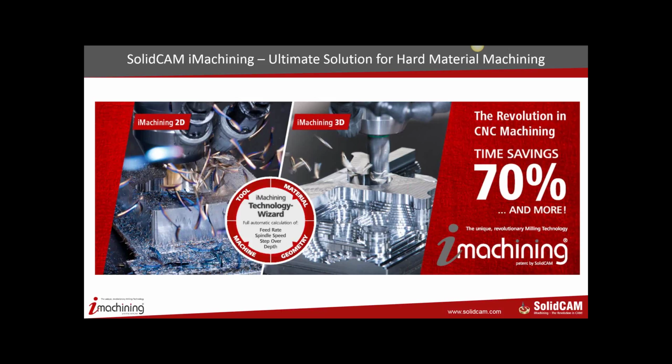With titanium and Inconel, a small variation in the cutting force acting on the tool can be catastrophic for the tool itself. A small change and you'll have a tool disintegrated right in front of your eyes. So the cutting force is one of the major things iMachining gives to the machining world: the constant cutting force principle.